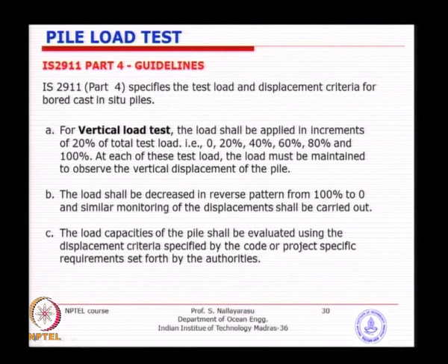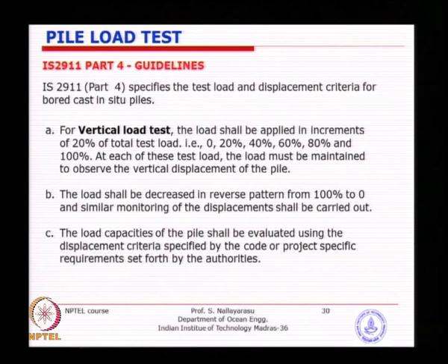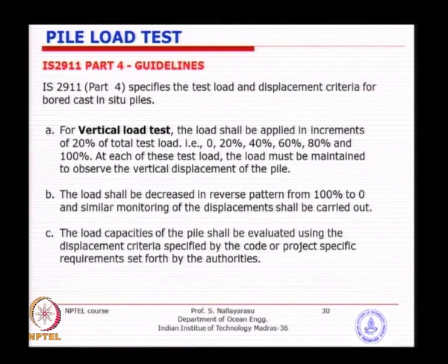So what the codes are suggesting, instead of what we saw, which was 25, 50, 75, they have divided the loading into 5 sub segments, 20, 40, 60, 80 to 100. So that is just a little difference, and basically the loading unloading cycles are almost similar. I am not very sure whether I have copied the time cycle. You can look at the code, the times are also given, 30 minutes up to 6 hours.